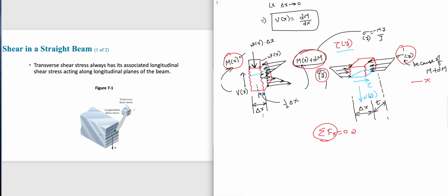So how do you convert stress to a force? You multiply that with area. So sigma of y on the left hand side times dA. Why am I writing dA? Because sigma is different at each point, so we have to take area integral so that we get the total force.